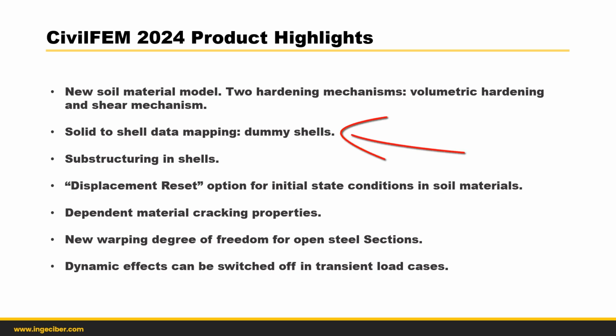Dummy shells for integrating stresses in thin structures, that is, one dimension smaller than the two others, modeled with 3D solid elements. Therefore, this capability allows modeling wall structures with solid elements that provide more accuracy and details, and to obtain forces and moments, results only available in shell element models.